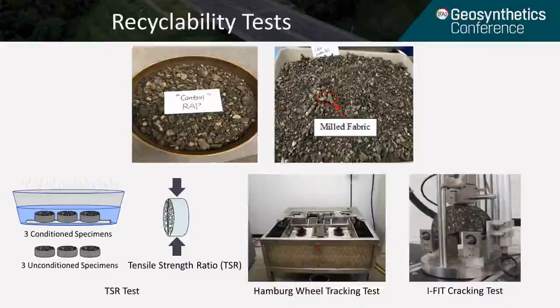We performed 3 performance tests, including tensile strength ratio test to assess moisture susceptibility, Hamburg wheel tracking test for rutting resistance and moisture susceptibility, and Illinois flexibility index test for cracking resistance.